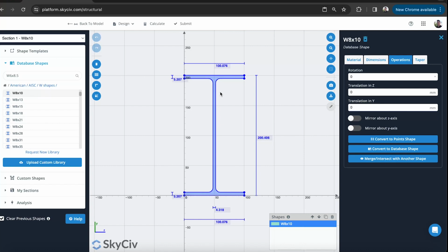because they do have a strong orientation or a strong axis, which in this case will be something equivalent to a down force in this direction, and then a weak axis, which in this case would be in this direction. So basically what that means is that this section can take a lot more load in the major axis or the strong axis, because if you put a down force on here, you're going to create a bending moment about the Z. And this section, since it has a really high depth and has a lot of material here, is a lot more capable of taking that bending moment in that direction, because that's what it's basically designed for.